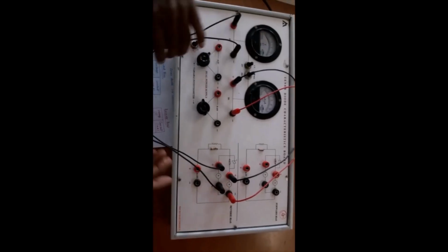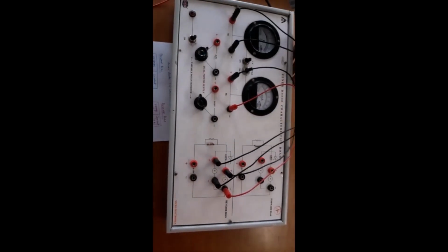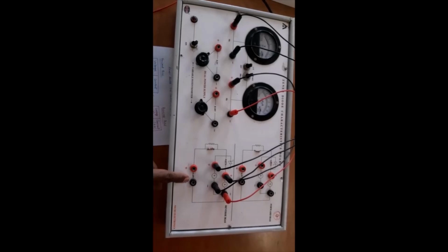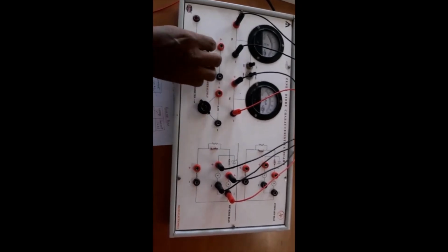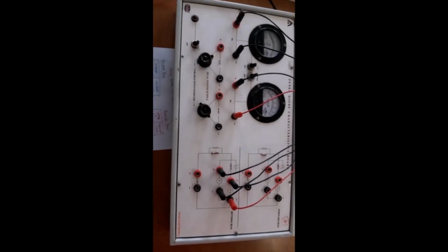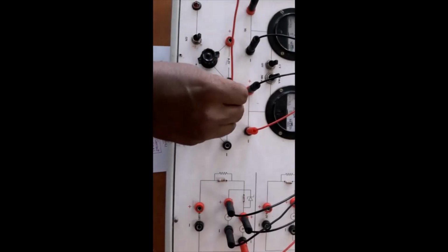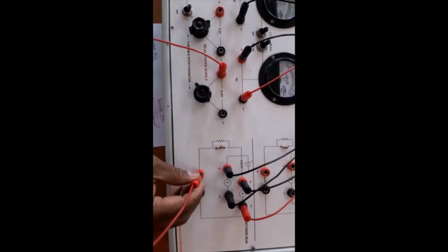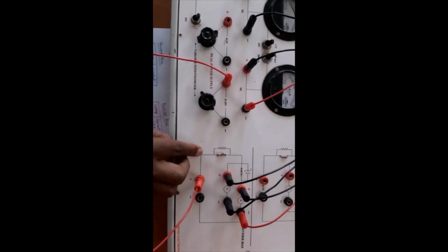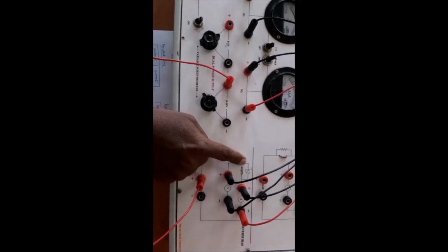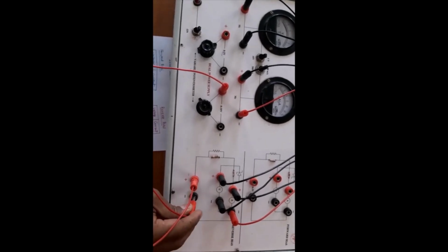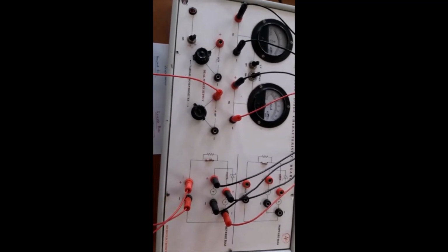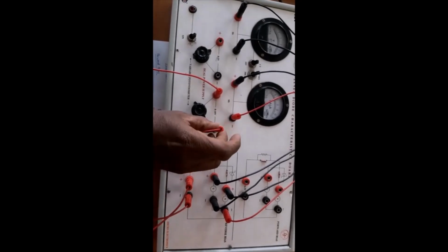Now we have to connect the DC supply. The DC supply is 0 to 10 volts. You need to add it here. We have the 0 to 10 supply here. Therefore, I take the positive of this connected to the positive of this, but this positive has gone to the negative of the diode. Therefore, it is in reverse bias. And I am connecting the negative of this one to the negative terminal of the source.